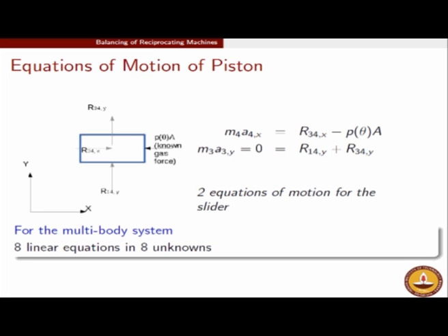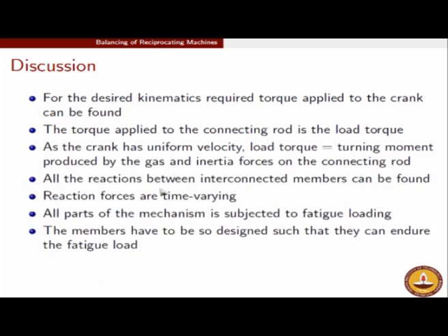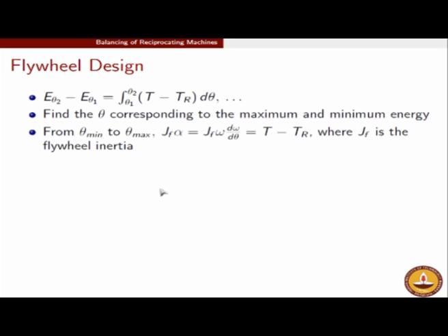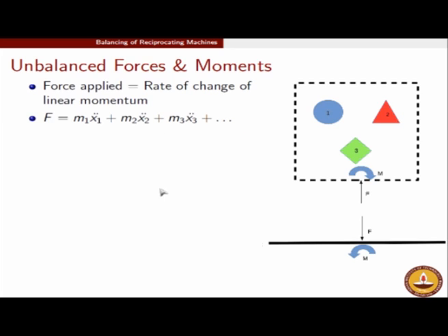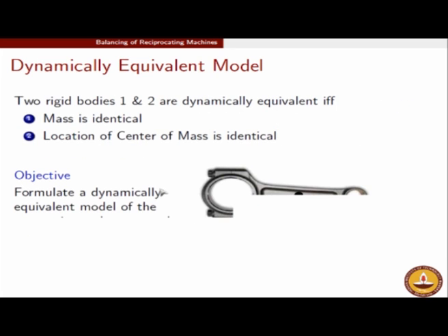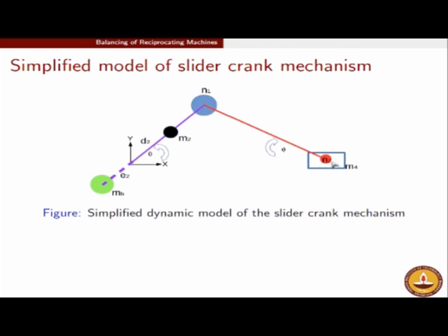Okay, another question. CEC Gurikrat is asking me why shaking moment is 0. Shaking moment is 0 as is borne out from the simplified analysis. In the simplified analysis that has been presented here, you will get to see that there are no inertia torques in this simplified model. In the simplified model, the rotary parts are completely balanced. There is only one inertia force. There is only one mass which is having any kind of inertia force, that is associated with the reciprocating motion.